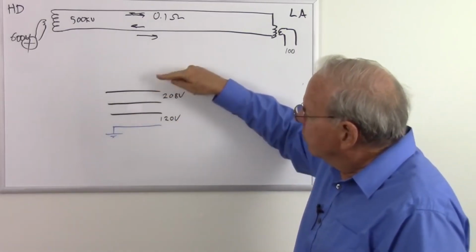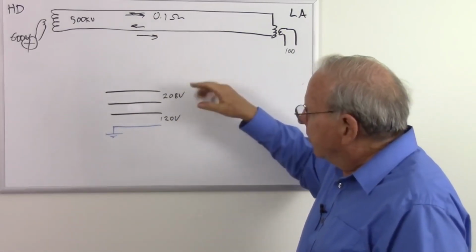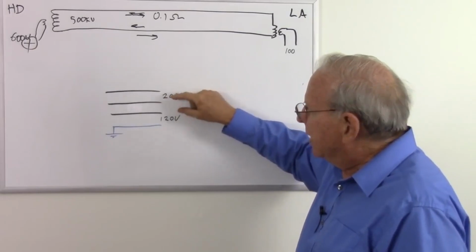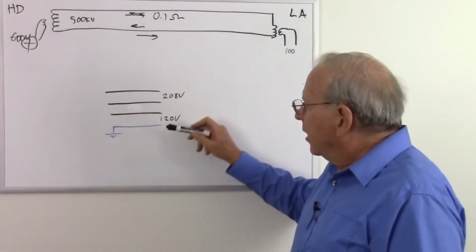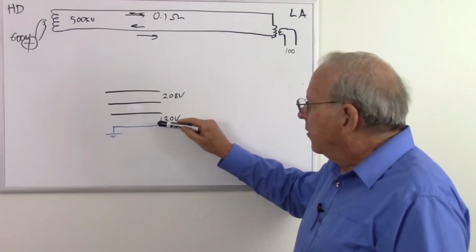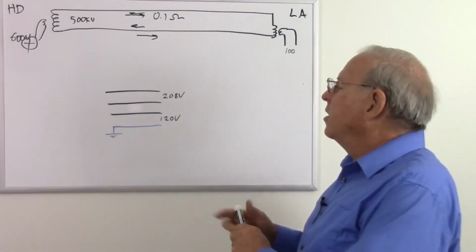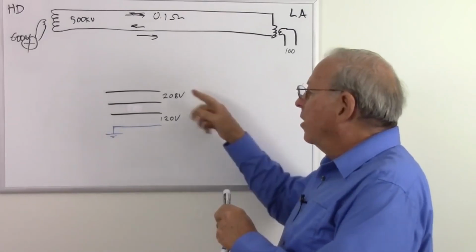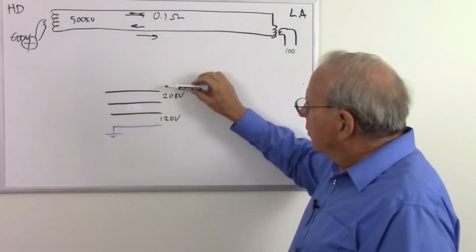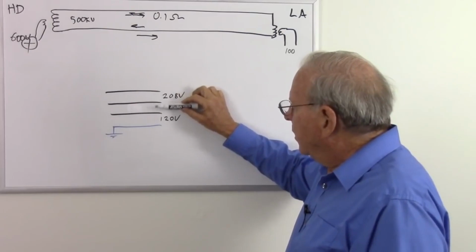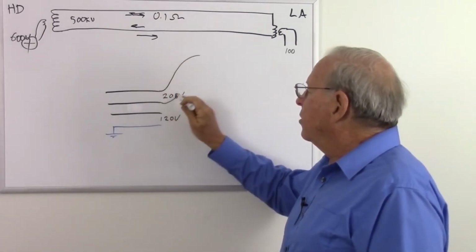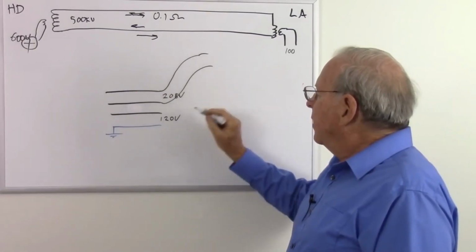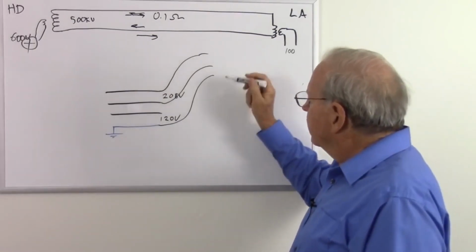Well, because of course the voltages are happening at different times, it works out so that the averaging of the voltage between any two of them is 208 volts. So to get 120 volts, we take any phase and the neutral, but we need 208 volts to run industrial motors. To get the 208 volts, we will work between the phases themselves. And sometimes they will take this into a residential neighborhood, and they will take the neutral.